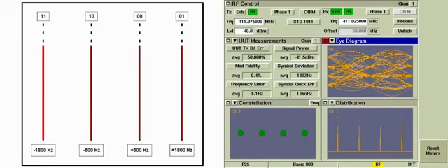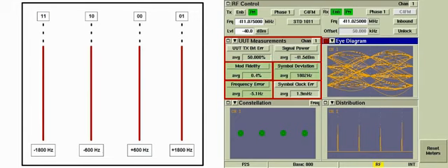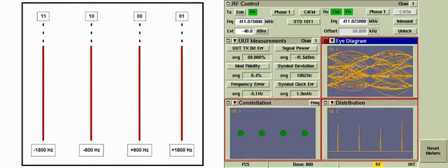The instrument's P25 test tile can be configured in a number of ways to obtain at-a-glance comprehensive views of test criteria. In this example, the UUT measurements tile is displaying the three main parameters of modulation fidelity: frequency error, symbol deviation, and RMS deviation error, displayed here as mod fidelity. The eye diagram, constellation display, and distribution plot are also selected for display. The input signal has near-perfect modulation fidelity characteristics.